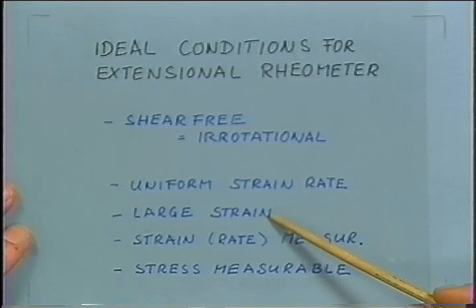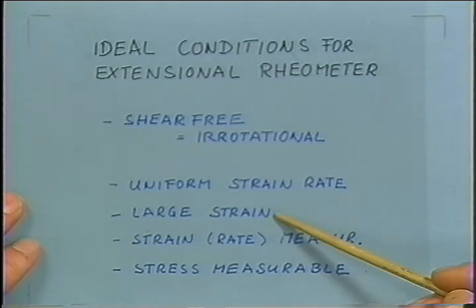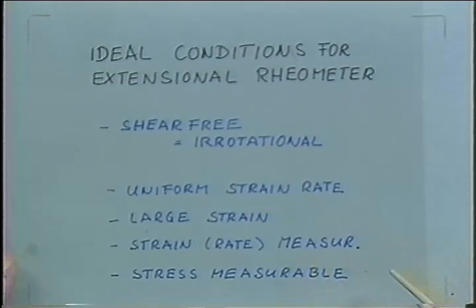We would like to apply large strains because the molecular changes are most visible as the extensions are very, very large. Also in polymer processing, the stretches are normally very, very large. So we would like to verify this. And for a material element sitting at the stagnation point in our kinematics, we can achieve large strains because just sitting there and we are stretching, and we can just go forever. In, of course, continuity, the continuum assumption tells us that's always the same material in there.